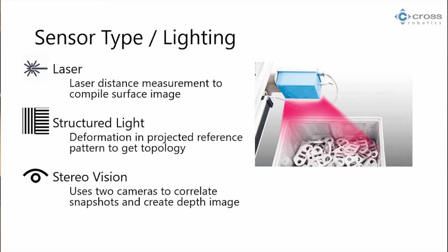With a laser, you can do profile scanning, so scan just in a line. Imagine you have, let's say, tubes in a bin just as wide as the tube, right? Or a cord of firewood. You don't need to do a full 3D image of the entire top of it. You just need to scan in a line along the middle, and then you can see which piece of firewood or whatever is the best one to pick. That's something you could do with laser line scanning, or you can do a 2D inspection by scanning that line over an area.